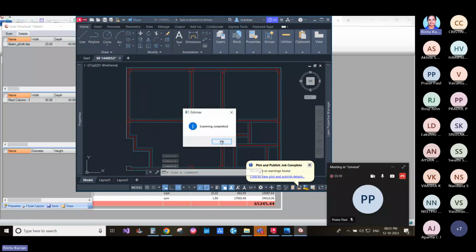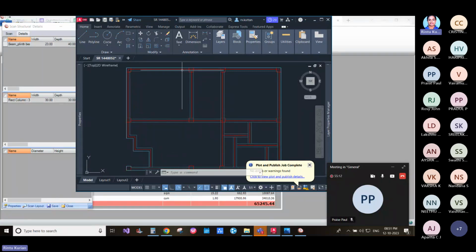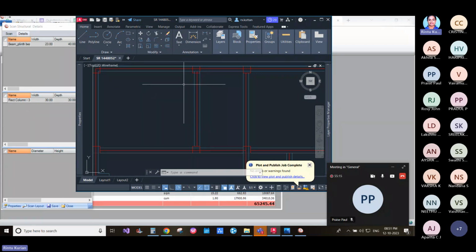quantity of materials. Now, by using center lines, what is actually happening? The center line length into width into height gives the volume of brickwork to be done. That is the main reason why we are taking center line of the wall. Similar calculation is done for finding the quantity of beam.